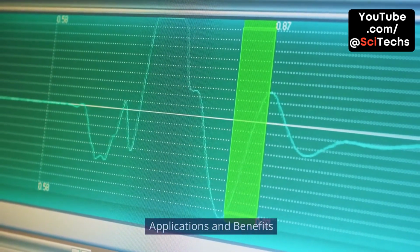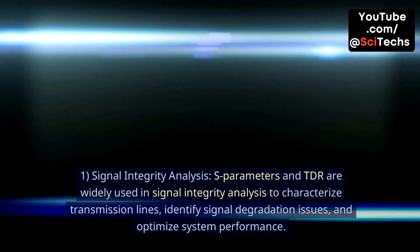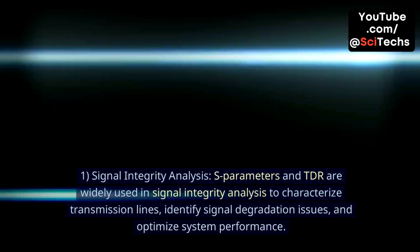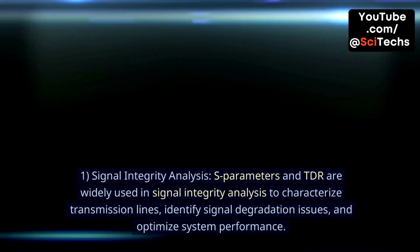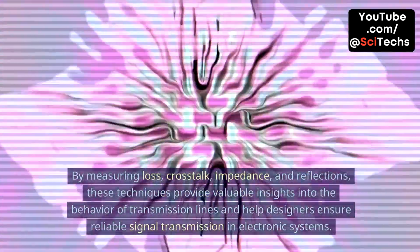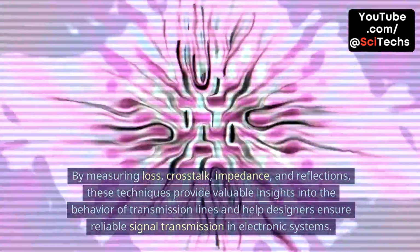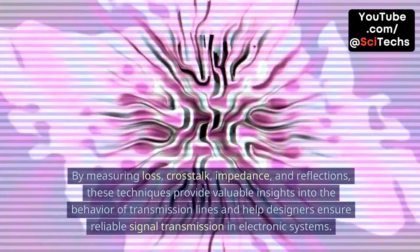Applications and benefits. 1. Signal integrity analysis. S-parameters and TDR are widely used in signal integrity analysis to characterize transmission lines, identify signal degradation issues, and optimize system performance. By measuring loss, crosstalk, impedance, and reflections, these techniques provide valuable insights into the behavior of transmission lines and help designers ensure reliable signal transmission in electronic systems.